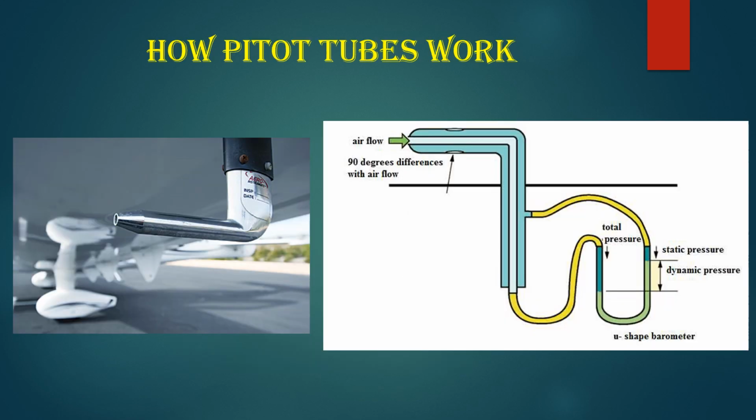A Pitot tube is simply a small cylinder that faces a fluid so that the fluid can enter it. Because the cylinder is open on one side and enclosed on the other side, fluid can enter it and cannot flow any further, and comes to rest inside of the device. The Pitot can be inserted through a small hole in the duct, with the Pitot connected to a U-tube water gauge or some other differential pressure gauge for determining the velocity inside the ducted wind tunnel. The difference between the two measurements determines the fluid flow rate.